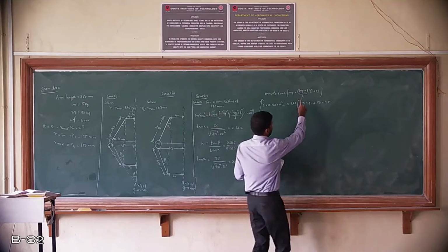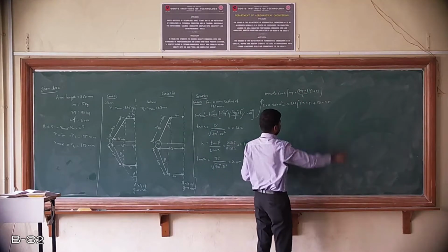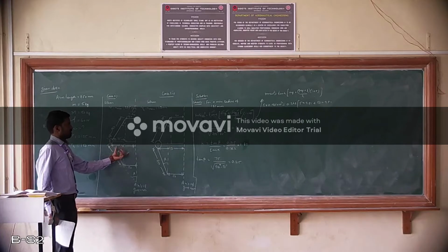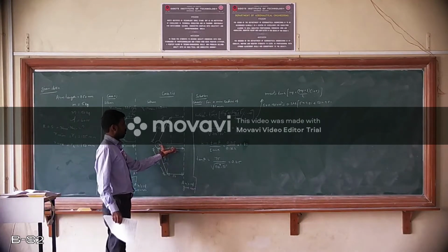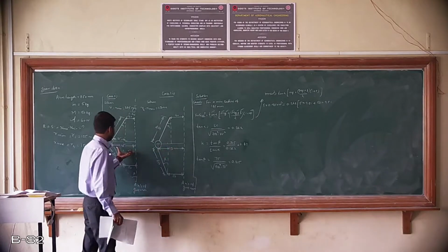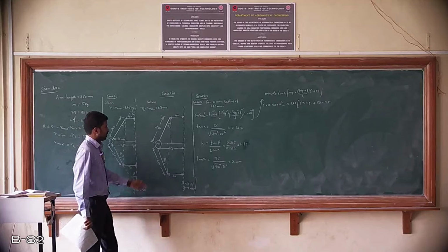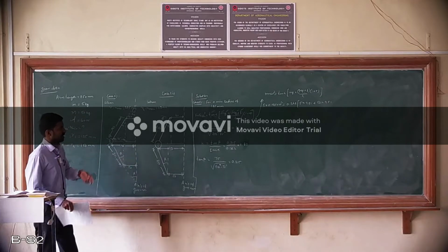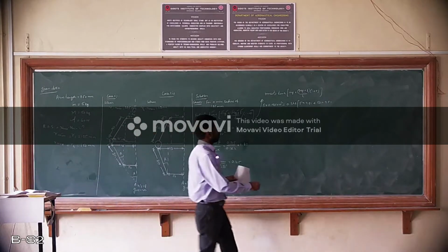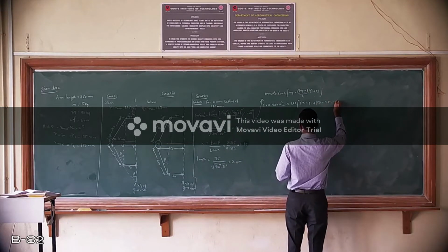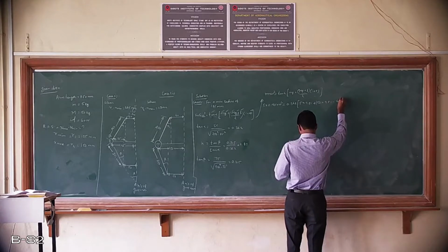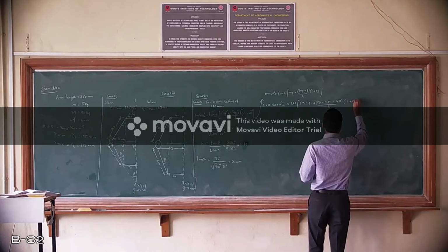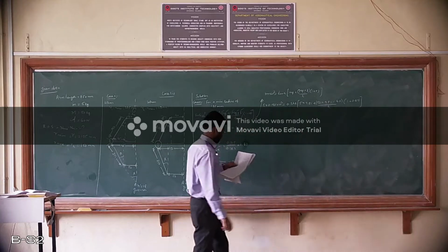Now the question is, the equation says mg plus or minus F divided by 2. So do we take it as positive or negative? For minimum radius, always you have to take the negative value of F, and for maximum radius, always you have to take the positive value of F. Why take negative and positive? We have already discussed that while doing the derivation for the Porter governor. So I will take minus of the force of friction, that is 40, divided by 2 into bracket 1 plus the value of k, which is given as 0.87.